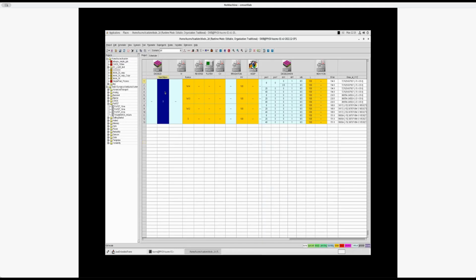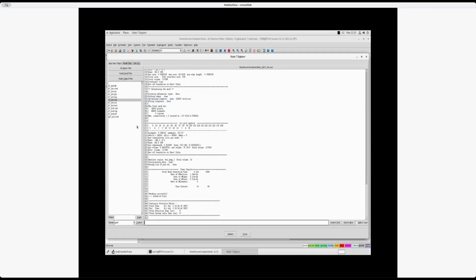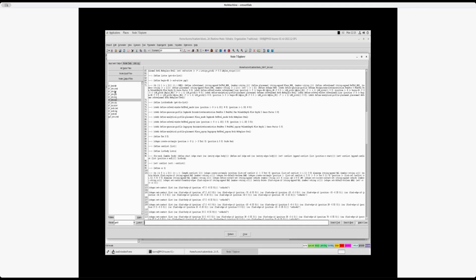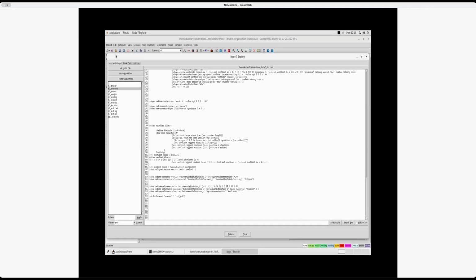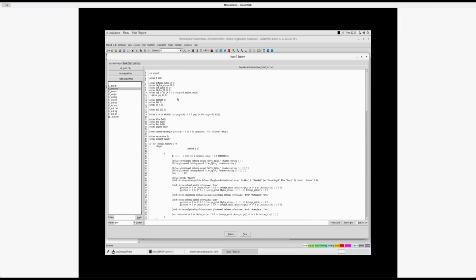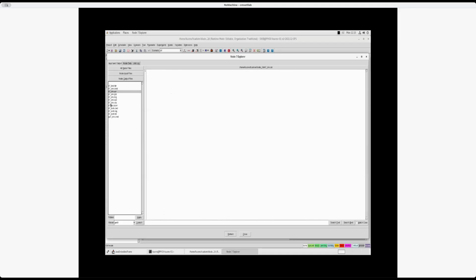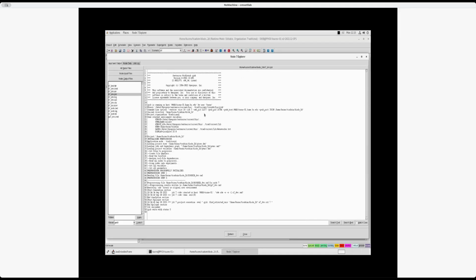So I can click on that node, and then you can double click. And then you're going to have, as I mentioned last week, the node explorer that is going to pop up that will allow you to see what happened in that simulation. So you have all the files that I mentioned, and now we can see this is a real node, right? So it's node 7. The file was generated as node 7.dbs, which is device simulation in that case. And then we can see the script. This is essentially the script that I defined earlier, but the numbers that I had in @ have now been replaced by the real number. Then you have the error, so there was no error during execution, so there's nothing in there.